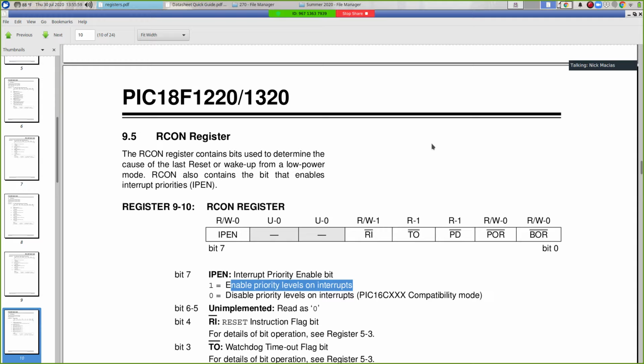A while loop would really just be a branch, maybe with some kind of test condition and a conditional branch, but you don't necessarily need an interrupt for that. But anything that's interacting with outside hardware, with something that can change state outside the system, is probably a good place for an interrupt.